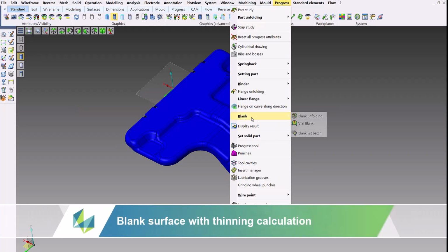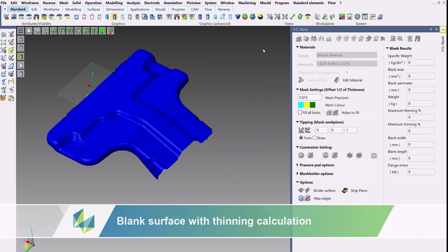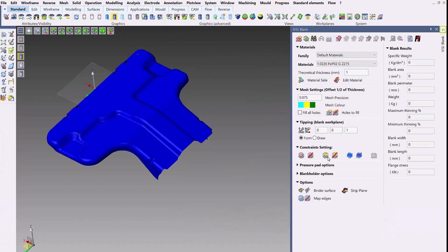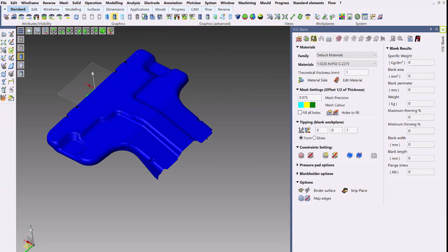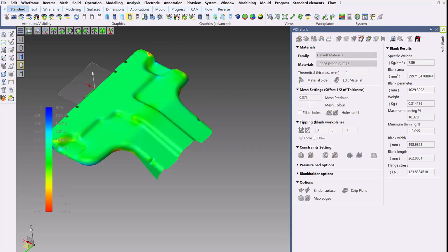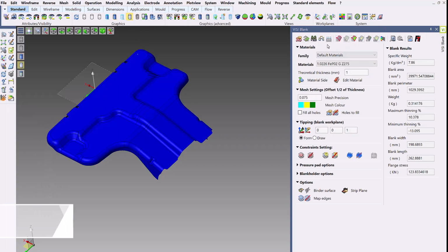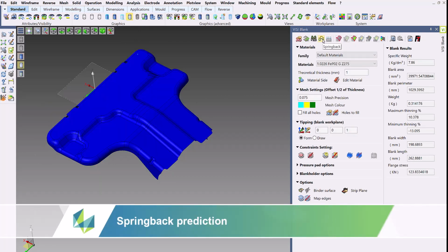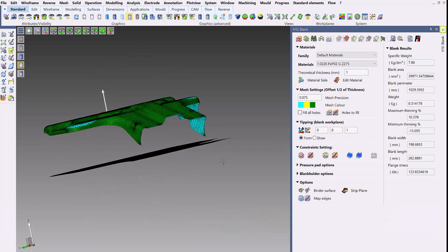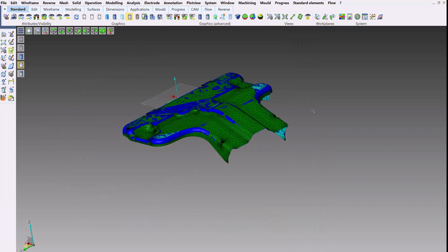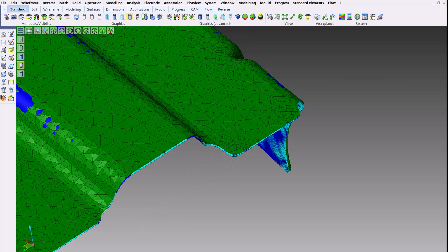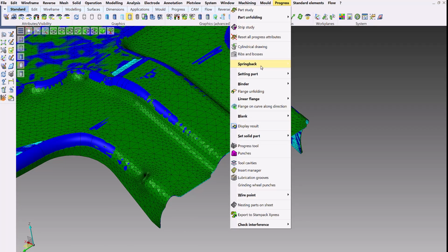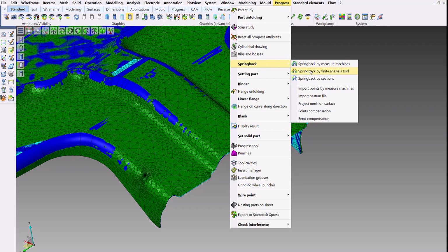For a sheet metal stamping to retain its shape, it must be adequately strained. This means you must form the metal in a way that imparts work hardening. If you don't have adequate strain, the material wants to return to its initial state. We call this effect springback. Springback is one of the most complicated behaviors to master and control. Many factors influence it, including material properties, thickness, geometry shape, forces, and strain distribution.